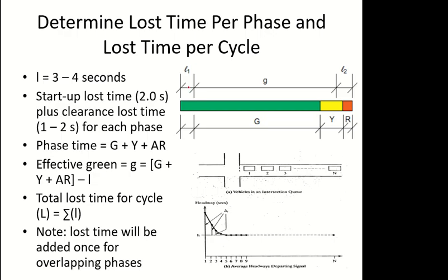And most of the cars will do it, right? The first 3-4 cars need this time to get moving. The cars which are behind already see the signal green, so they become ready. Okay, so the startup loss time is in the first 3-4 cars.